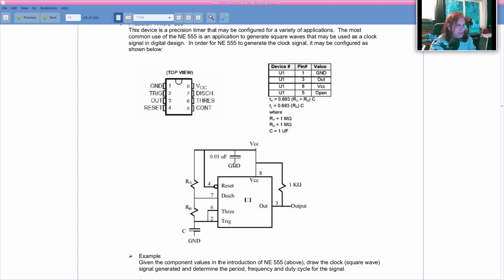And then we put this little tiny capacitor, 0.01 microfarads, farads are units of capacitance, between power and ground. Again, it's not going to create a short because inside a capacitor there's no direct connection from one lead to another. There's a little air gap. But as voltage between here and here starts to change, we get a little bit of current flow. This is called a despiking capacitor. All right, and then pin 8 and 3 we connect through a 1 kilo ohm resistor. And then we take our output on pin 3.